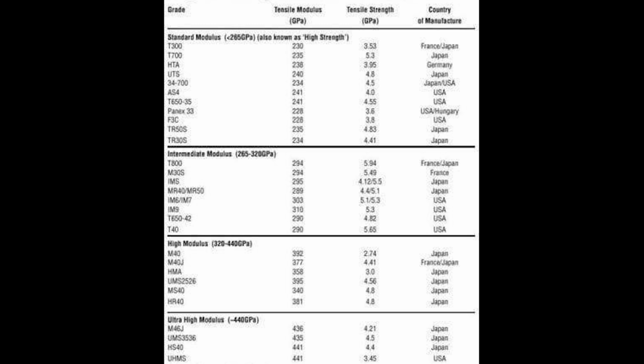So this weaving technology, the spread tow, means that you're taking one of these yarns with 12K or whatever, and then you spread it into a very wide tape, meaning that it gets very thin. And then you can weave with these tapes, and you get a very thin fabric made out of these stronger and stiffer fibers without making a fabric that is super thick where your fibers are bent all the time.